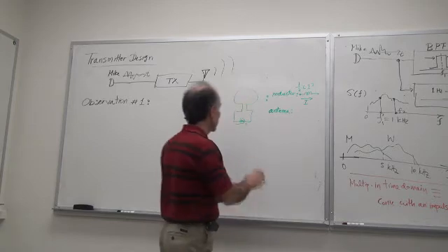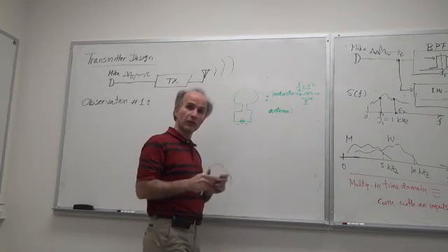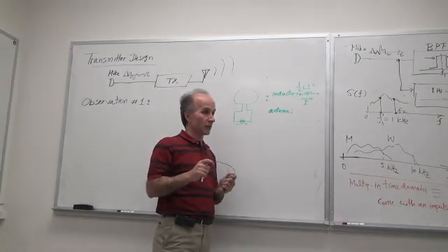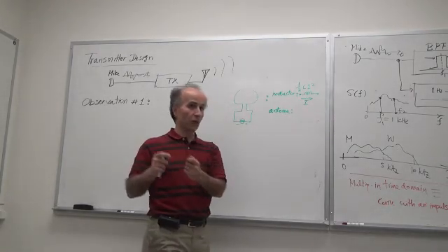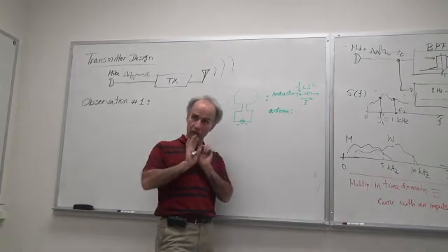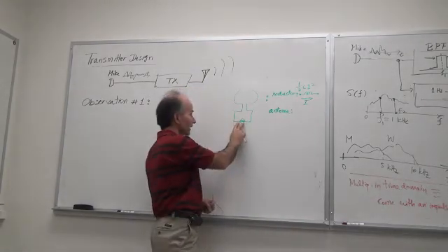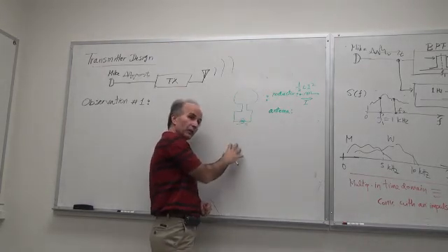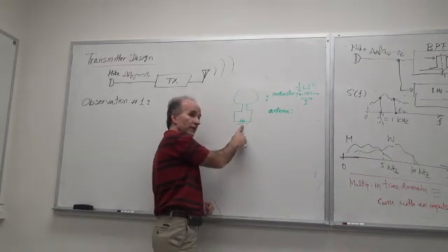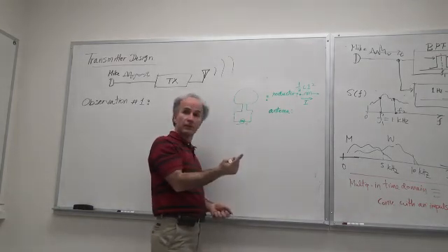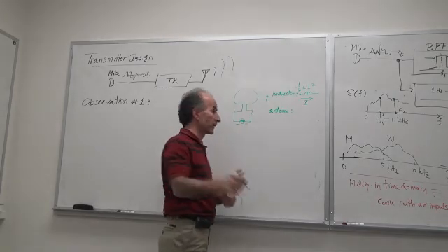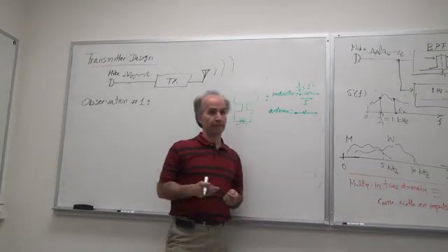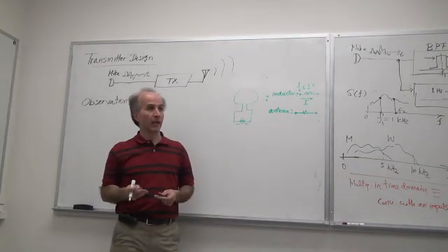Well, in a perfect antenna, if you apply voltage to it, you give it energy, what is that antenna supposed to do with that energy? It's supposed to radiate. It's supposed to go away. So every joule of energy that this source gives to the antenna disappears. It's not stored here. It doesn't come back. It's not retrievable anymore. So as far as this voltage source is concerned, the antenna looks like a resistor, because you gave it energy, then it disappeared. So a good antenna is modeled by a resistor. Okay? And that makes sense.